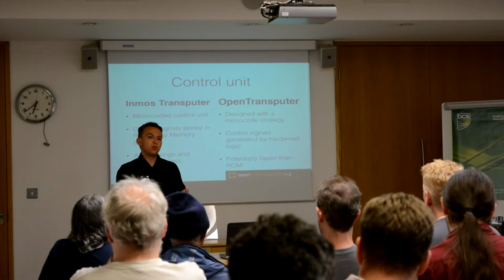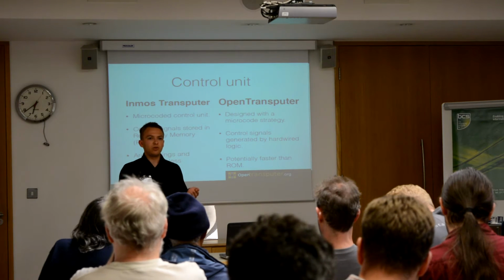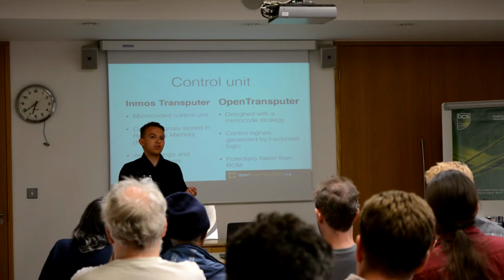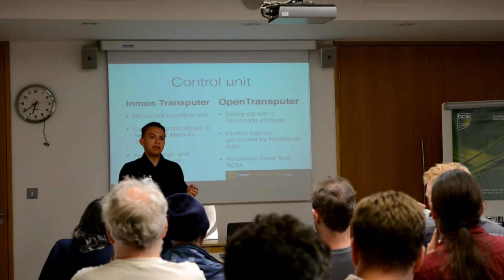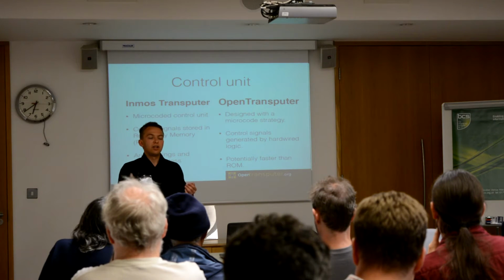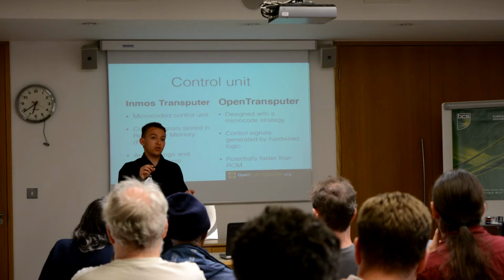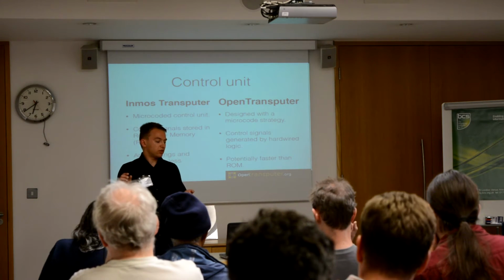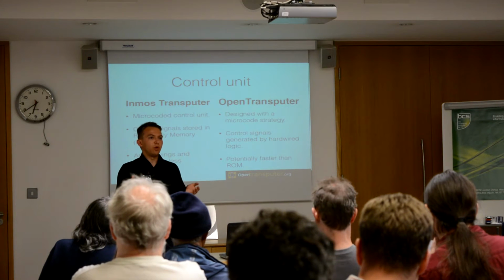In the OpenTransputer, we developed the control unit with a hybrid approach. We designed it with a microcoded approach, but the actual control unit logic is implemented by hardwired logic. Hardwired logic means we use actual blocks of logic to generate the control signals at each clock cycle. And so this means we get the best of both worlds.